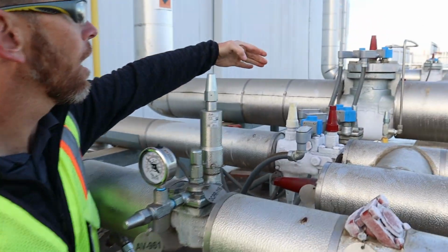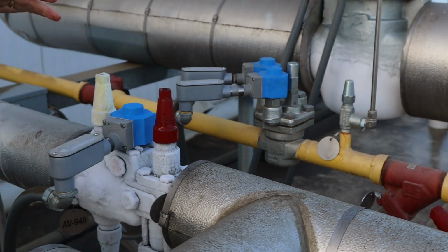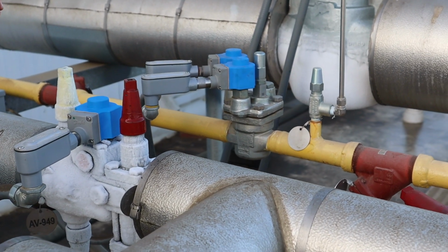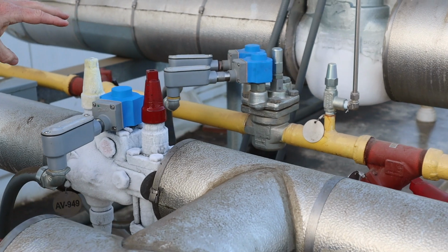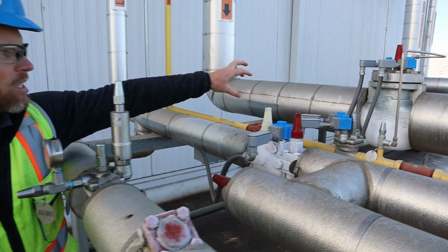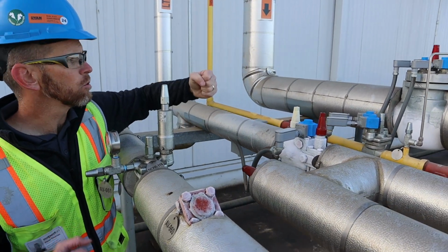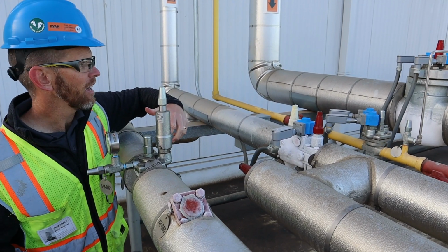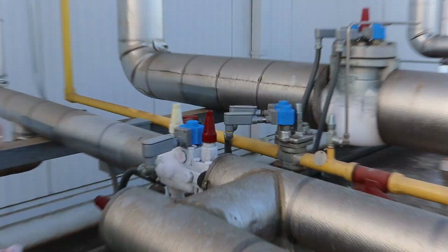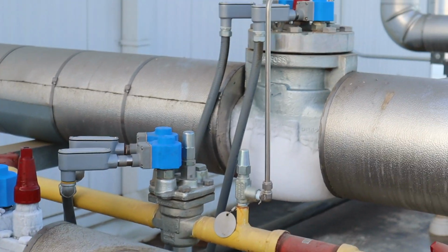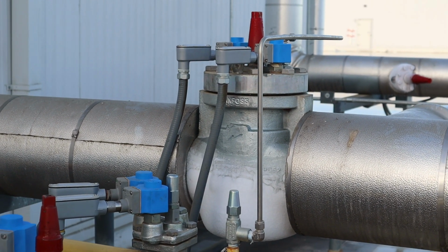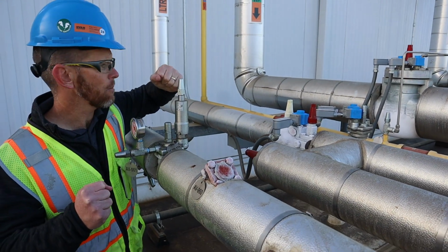Moving on, behind that is the hot gas solenoid valve, and this is an advanced form of hot gas valve that has the two solenoids you see there, because it's got two stages. The preheat stage opens at about 10%, and then the second stage will be fully open. And then the big valve there is the suction stop valve. Again, it has a couple of solenoid components for various stages that it could be open.